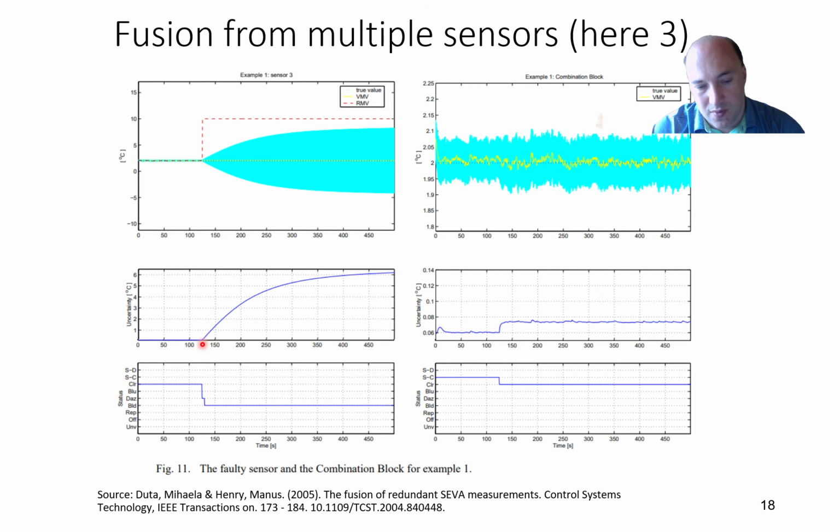Then they have introduced some error at some specific time, and we can see that this uncertainty started to increase, and it first went to the dazzled state for a short period of time, and then it went to the blind state. So in the blind state, we know that we are operating on historical data, so we know that this is only our imagination, that it's there, and that the real measured value has, for example, changed like that with a step change. And during all this time, we can see that this sensor 3 is in the blind state. The other sensors are fine, they are all in the clear state. So we have 3 sensors in total. 2 of them are in the clear state, and the third one is blind from this specific time.